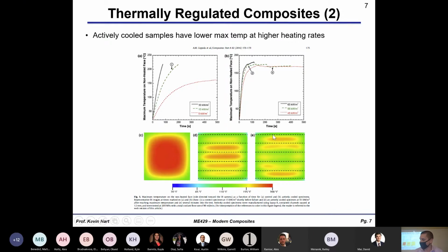So just by having this active cooling, where he's got the channels running through here and some coolant running through here, he's keeping this composite cool and in a temperature where it might actually be serviceable, all right? So that gives you the ability to operate in temperatures that you might not have been able to before with a polymer matrix composite. So pretty cool stuff.